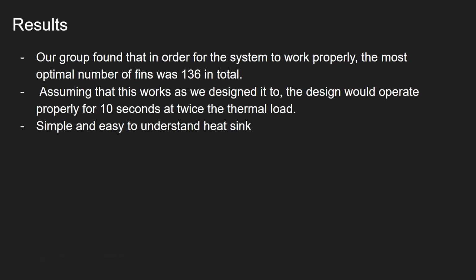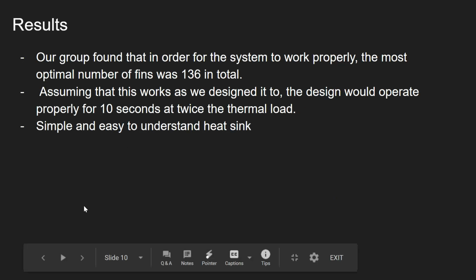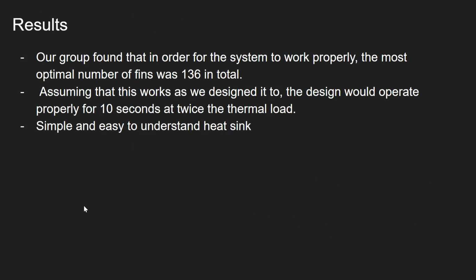In the end, our design worked properly and completed the requirements for the task. We were able to determine the total fins required, which was 136, and we were able to prove that the design could in fact remain viable for at least 10 seconds during the overload. If we were to come across this problem again, we might have tried to make the fins longer, or even change up the material to see how it affected our results. Our choice to use a square base and fins rather than a circular base and pins was beneficial to the overall simplicity of the design and made for a simple yet powerful heatsink.